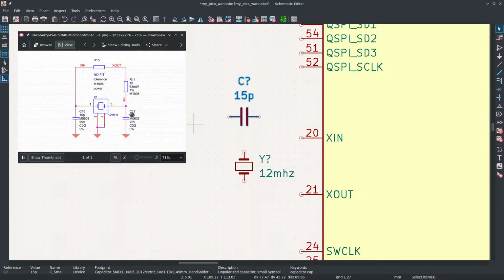So we are basically making a handout of the board design. We have to design the schematic first, and then we're going to make the design for the board itself and put those together. We're going to send them out to a manufacturer that's going to make them. We're not going to do their assembly service because it costs more money than we can afford for the workshop. So it's probably going to be me soldering on the hard-to-solder components for everyone, and then everybody can solder everything else. The microcontroller is particularly hard to get right because it has no leads on it.